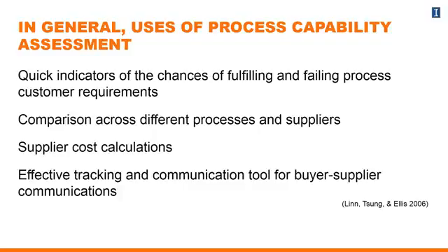Thinking about it in terms of process capability ratio, an index of 1, a minimum of 1, tells you whether it's going to fall within specification limits or not. It gives you the ability to compare this particular metric across different processes. If you have different suppliers who you're considering or comparing, you want the CP and CPK to be higher for the suppliers that you choose.